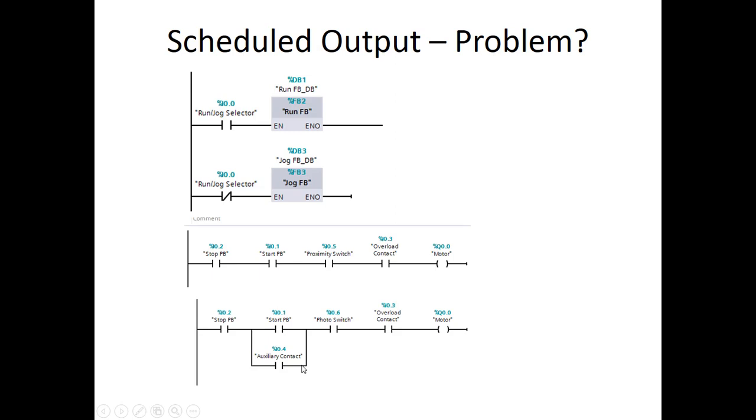Here's another way where we schedule the output twice. So this works. Not a big fan of it. Basically, put this same logic into the routines, and the selector does one or the other, and therefore the motor is going to be running or not running. And so the problem is that we've used the output more than once.